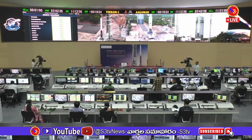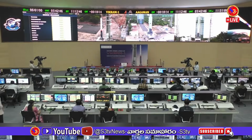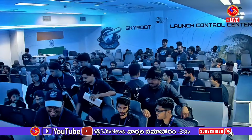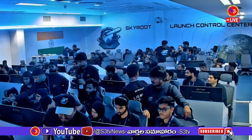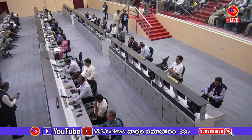That's true, Suyash. So, an update for our viewers. Just a while back, we got a confirmation that the guidance, navigation, and controls team have successfully completed gyro compassing and the static navigation profiling of the inertial navigation package. This is done so that the rocket knows its initial orientation with extremely high accuracy. In the process, the inertial navigation system determines the initial attitude of the vehicle by identifying the true north and the gravity direction with respect to a rotating Earth reference frame.